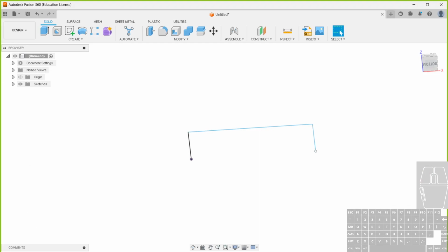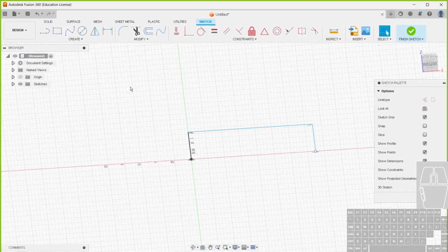And so I'm gonna go back here, edit the sketch, and now when I dimension this, I want it to be 10, so I'm gonna do 10 plus pipe diameter, or minus, right? If I want this to be the outside, 10 minus pipe diameter.